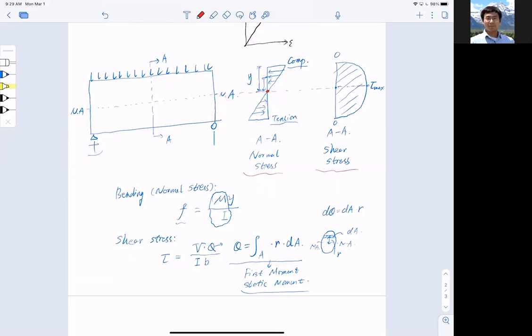So if I draw a small element right on the neutral axis, element 2, I can conclude that element 2 is in pure shear because there are no tensile or compressive stresses on it. Then if I move up, and pick a random spot in the upper portion of the beam, it sustains compression stress and shear. So this surface goes up, and this goes like that. For 2, it's pure shear, so it goes either way, but let me draw the direction this way.